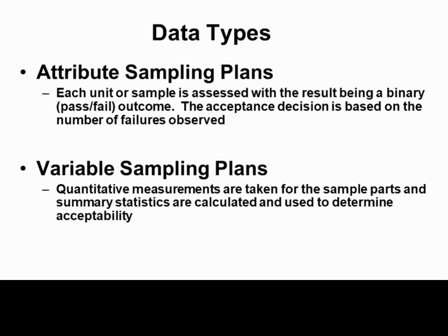But just to be clear, for attribute sampling plans, when we identify a sample size, it means that each unit we look at as part of that sample will have to be assessed, and the result for each assessment is either a pass or a fail. There's not going to be a dimension, like diameter or length or tensile strength, that we write down. It's either acceptable or it's not.